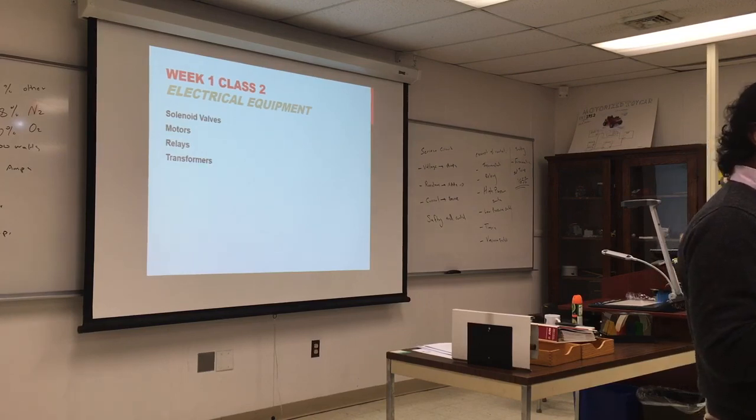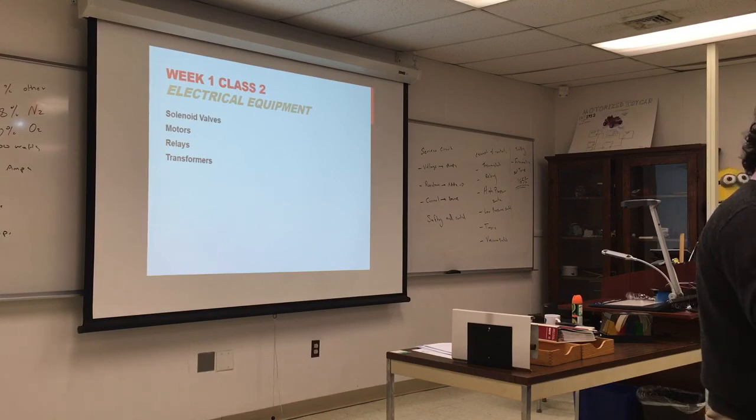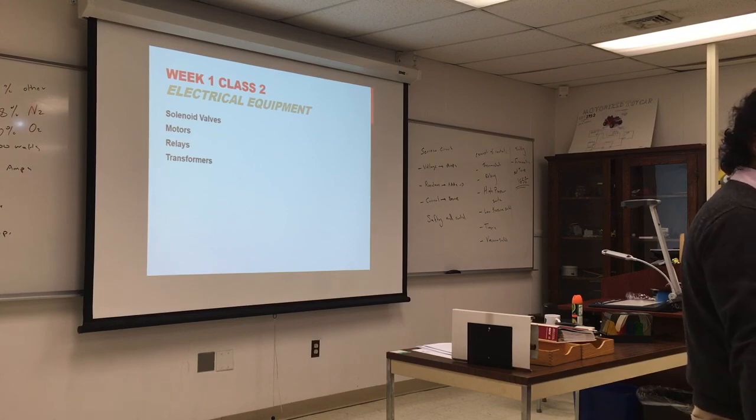Yeah, so if you have an indirect water heater that is heated by your boiler, you probably have one of those as well. This will have a thermostat that will turn it on, and it also has an aquastat. This aquastat will maintain the water inside the tank within those two limits, which are 140 and 180. So you're going to take water from that into your shower. Once it drops below 140, it will turn on the boiler.